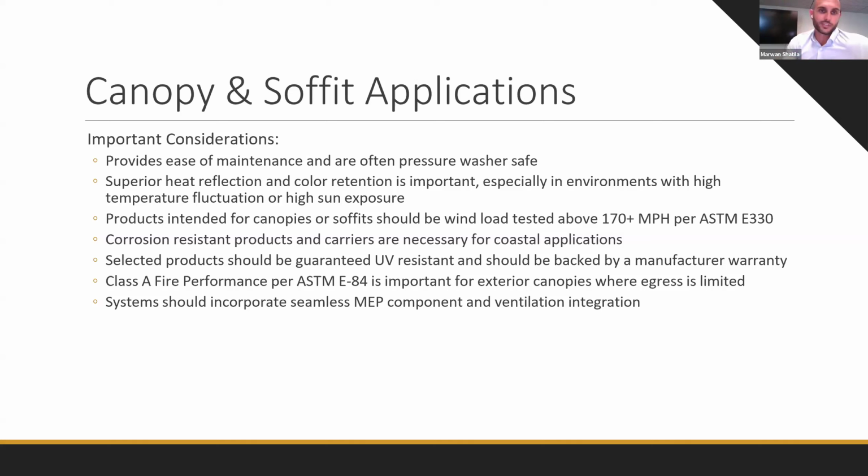This is just going to be a brief summary of some of those photos, much of which I've already discussed. Another key aspect is wind performance whenever you're designing with an exterior grade system. There is another slide later on that really harps on this, but for all intents and purposes, this is built and engineered to withstand very high velocity wind loads in conjunction with the carrier system. Again, this is very suitable for coastal applications as well, just because it is a polymer-based solution. And so for those reasons, it becomes very advantageous whenever you're trying to avoid things like rust or corrosion.